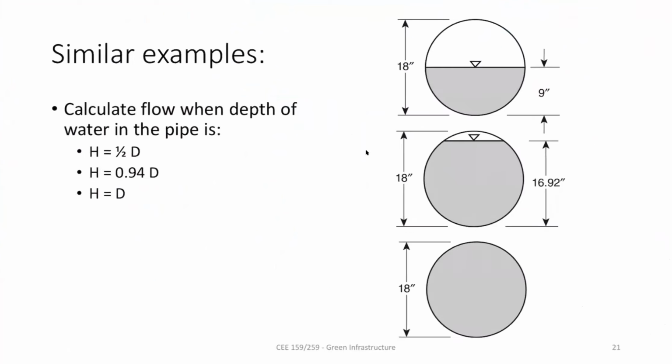As I said, as the height of water increases, the pressure on the wall will increase, because pressure depends on the height of water. So H rho G, that's what we call pressure. This is the maximum pressure. So that pressure depends on height. When the height increases, you need to have enough structural support so that it doesn't break or fall down or topple. So that's why it's important to calculate the maximum pressure on that side.